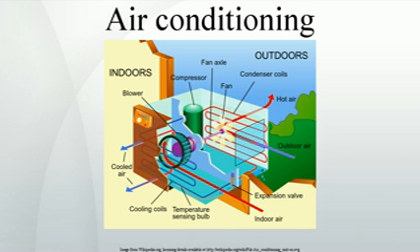In central air conditioning, the inside heat exchanger is typically placed inside the central furnace AC unit of a forced air heating system, which is then used in the summer to distribute chilled air throughout a residence or commercial building. A mini-split system typically supplied chilled air to only a single space, and thus was sometimes referred to as split-system single-zone air conditioning. Today, however, one split-system compressor can supply chilled air to up to 8 indoor units.